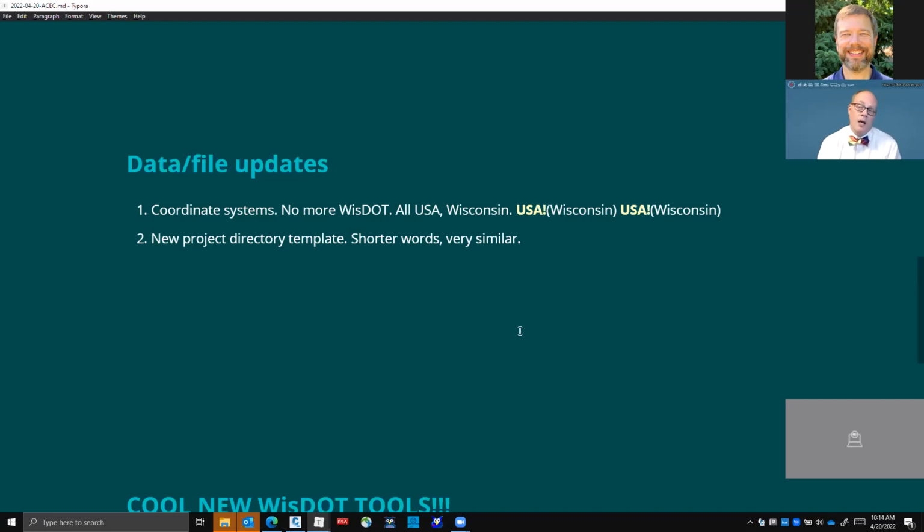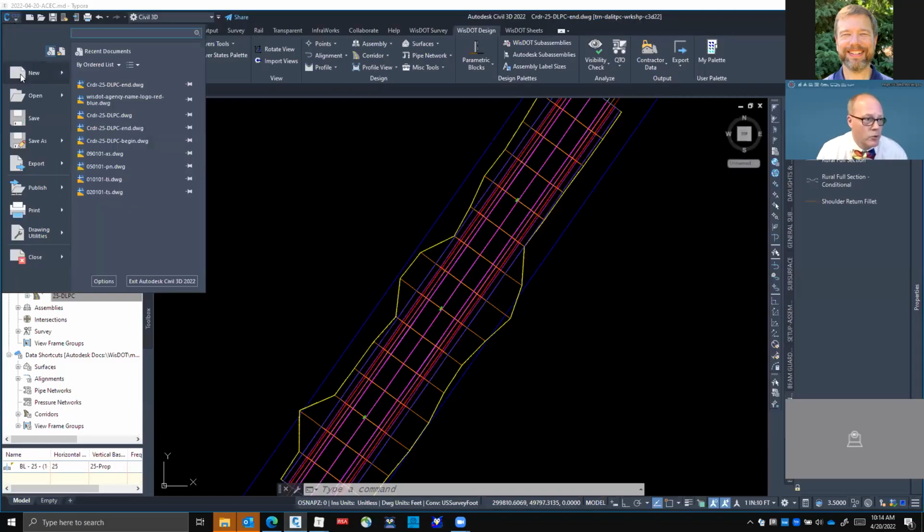So that's like, if you're using like Bing imagery, you're gonna have to use it. If you're using some GIS data from the state or from some federal source, or you got some ortho imagery and some kind of weird thing, you'll need to. If you're all in county coordinates, the vast majority of our projects are county coordinates. If you're grabbing data from the county and they're doing US foot county coordinates too, you don't need to be dealing with projections. But if you do need them, you want to use them.